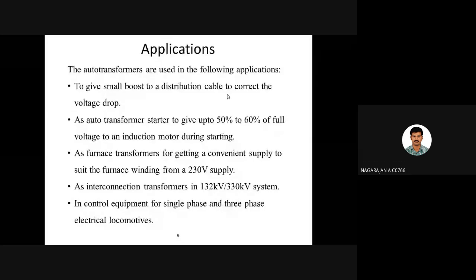Okay, now I put the regulator in position 2. What is happening now is 2 resistors will be cut out. Only 3 resistors will be remaining in the circuit. So at that time, the resistance is reduced, so I can get more voltage from the source. For example, now you will be getting around 70 volts. So initially you were getting 30 volts, now you will be getting 70 volts. This is for an example, don't write this. So the fan will be running at a better speed than the initial case. When you put it in 3, resistance will reduce more, so we'll be getting more voltage, and the fan will be running better than that.